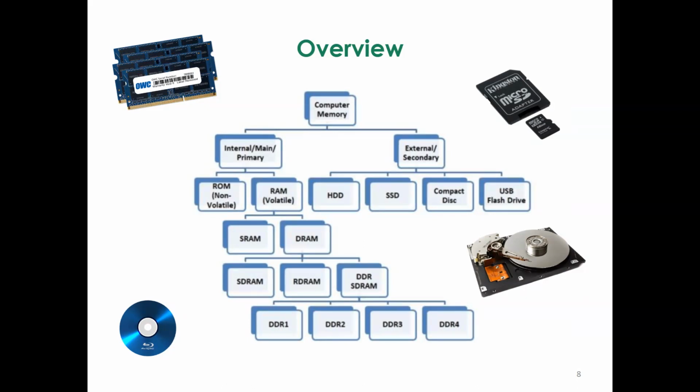For example, the code that boots up your phone is stored in ROM by the manufacturer of your phone. Then you have RAM as well, which is volatile. You write to it, you power it off, it loses what you wrote to it. And it also has multiple classes. The faster one, your SRAM, built from flip-flops, compared to your DRAM, built from capacitors.